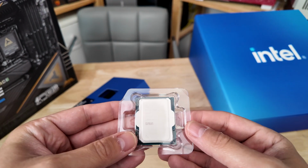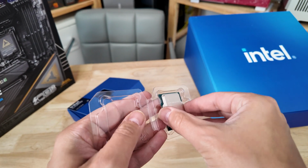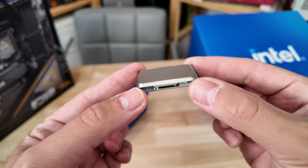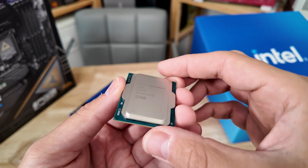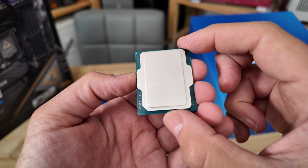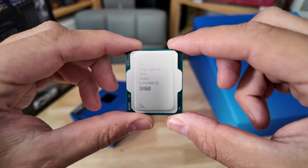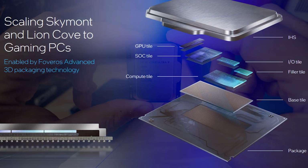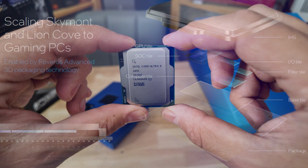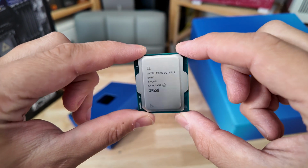So, pretty much identical looking processor to its predecessor, the 14900K, and you'll probably be able to find some more analysis out there of these things, but looks like a pretty thick substrate down there, so I'd imagine that Intel would have improved the substrate to make it a little bit stronger, because obviously we had the bending issues and all that kind of stuff last time. Underneath here, there was actually a spare tile, because obviously they're using the Foveros 3D stacking technology in these things now. It did have a spare area, and it had to fill it with a filler tile, because obviously they're really concerned about just having a flat surface underneath the heat spreader.